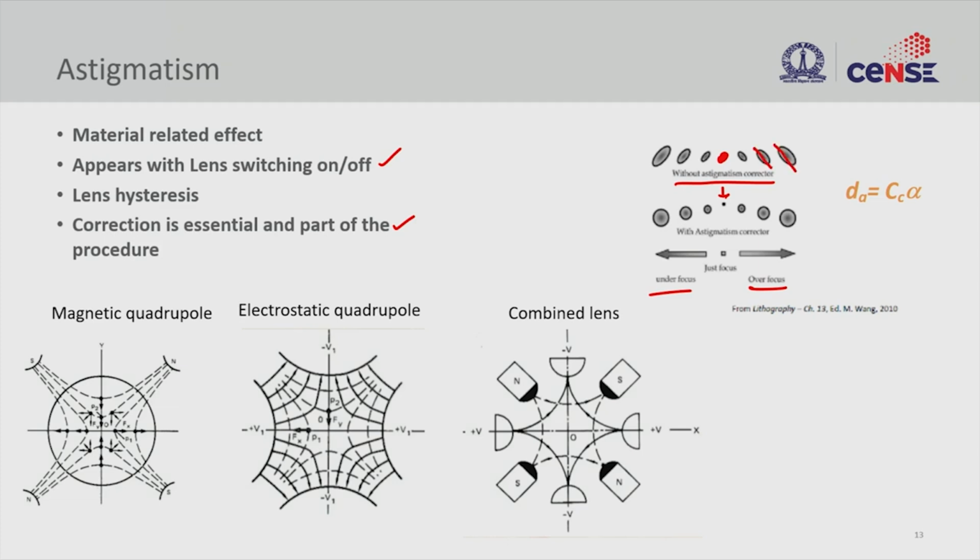This tells you that the lens is not aligned properly. So there is a preferential elongation in one direction, magnification in one direction, the other direction you don't see it. So this is a classic example of how astigmatism affects your beam quality.